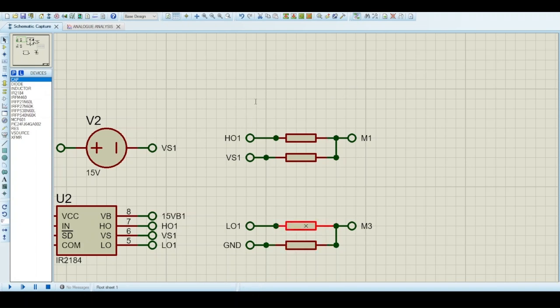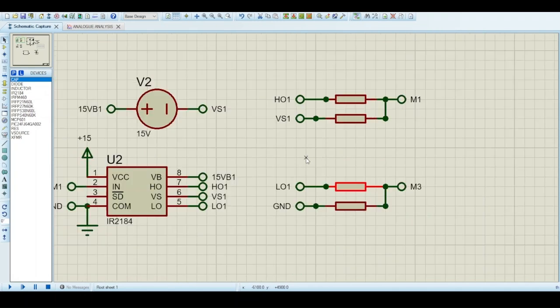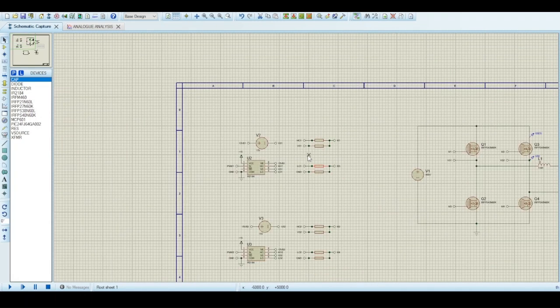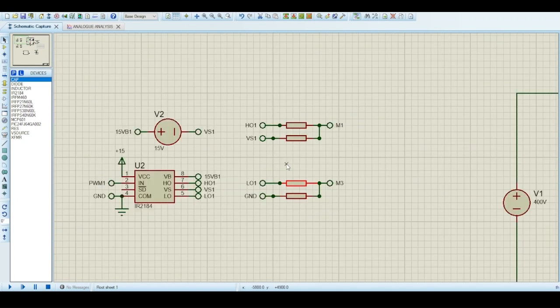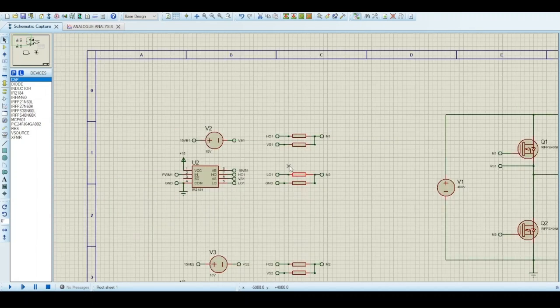And over here, I just made that resistance 56. It's important to note it's a balance over here. Obviously, if you go too low, then you might have ringing on the gate. And if you go too high, obviously it's not going to turn on quickly enough. So it's a delicate balance between the two. As you can imagine, the gate of a MOSFET, essentially what you're doing is charging up a capacitor on the gate. So it takes essentially charging the capacitor every time you turn on the gate of a MOSFET.